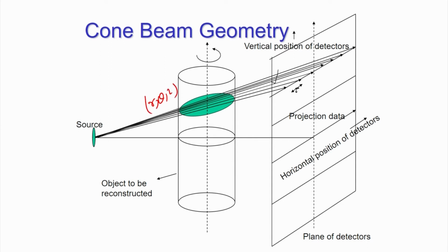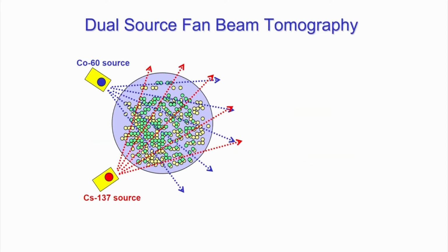Again it will save enormous time, because the time requirements are huge and systems are bulky. So, you have to have several theta motions. So, it takes huge time. Okay. While in cone beam tomography you can minimize the time further, because in one go you are scanning approximately the whole volume for the particular theta. So, that is about single source tomography or densitometry.